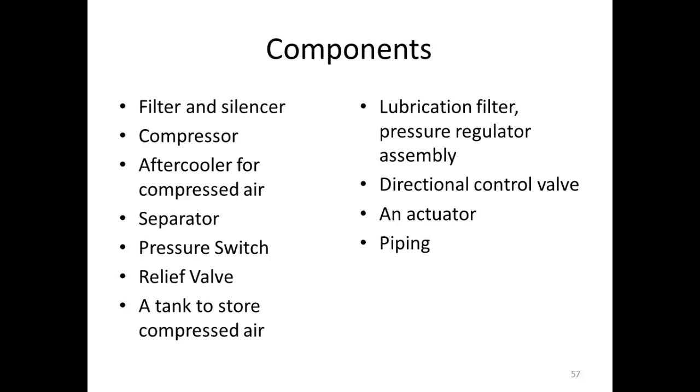So y'all got any questions? Like I said, we'll look at these. Directional control valves we touched on a little bit. Separators, we run into separators in pneumatics. Because we've got a problem with air: when we compress air, it can only hold so much water per cubic foot. If you reduce the volume of air, what's going to happen to the water?